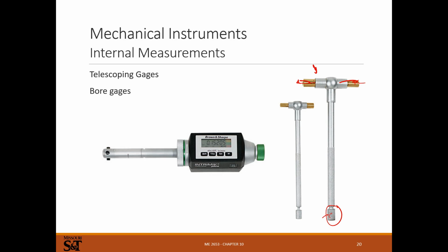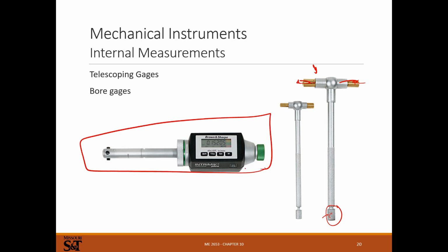They also make bore gauges. This would be an incredibly expensive piece of equipment here. Bore gauges usually are, for measuring something like cylinder bores and engines. It's an expensive piece of equipment. So they do make some micrometers that have pins that you can measure internal bores with, but it's pretty dedicated, pretty expensive. So internal diameters are a pain.